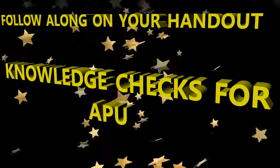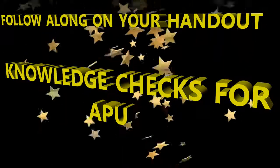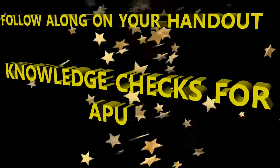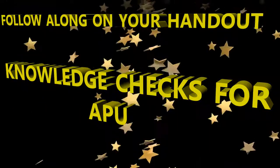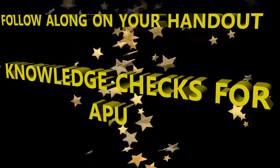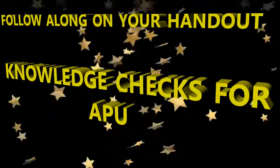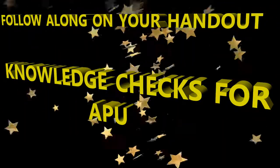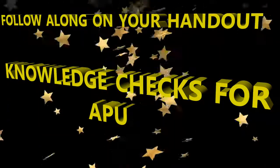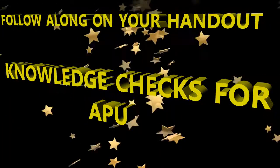Okay, let's go back to your sheet, and let's start with question number 1. I know it seems so simple, but I'm going to still verbalize it. Which power supply has priority over the other? Is it electrical or pneumatic? I remember I was saying electrical. Electrical supersedes pneumatic. If it came down to one or the other, electrical is going to be running. And by the way, electrical can operate at a higher altitude than pneumatic. So your max operational limit for electrical power is at 39,000 feet.